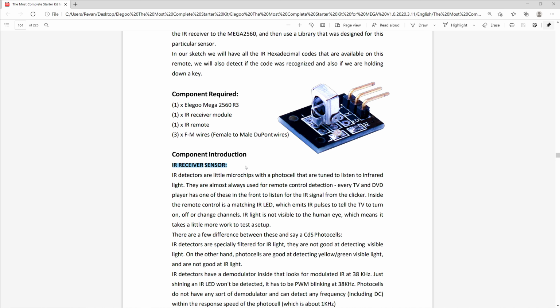They decide to give a little crash course on infrared in general. More or less, they explain that infrared detectors have little photocells that look for infrared beams at specific frequencies, and depending on the frequency it receives, it carries out a command. For example, an infrared receiver might be programmed to turn on a TV when receiving a 35 kHz signal, and reduce the volume when receiving a 36 kHz signal.